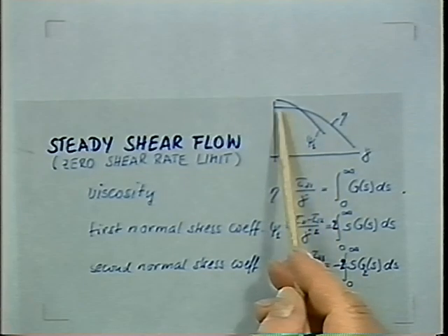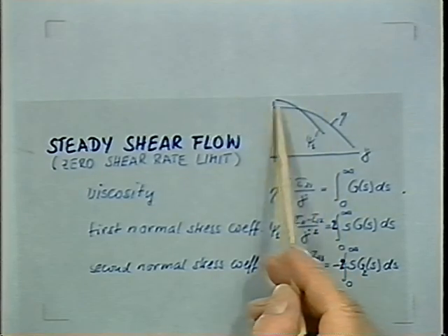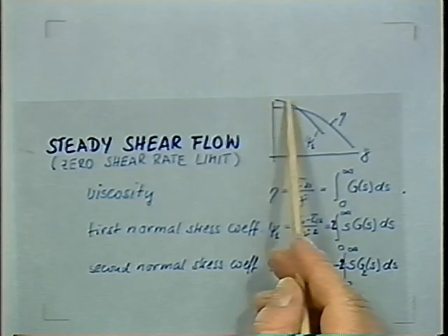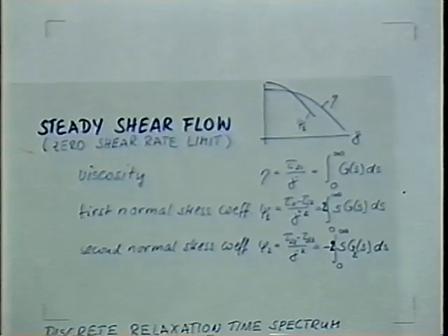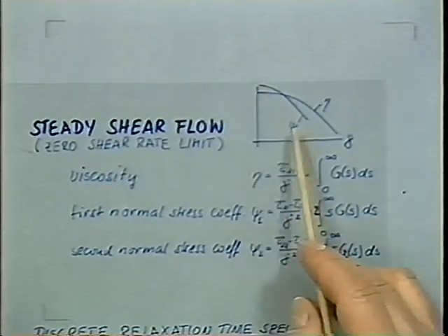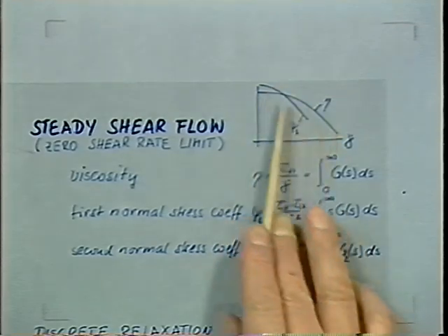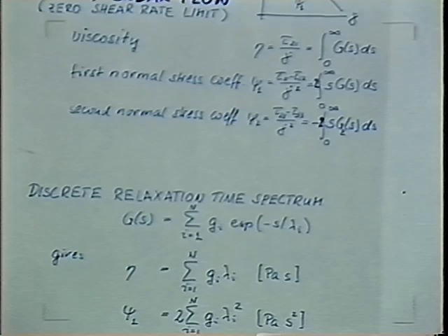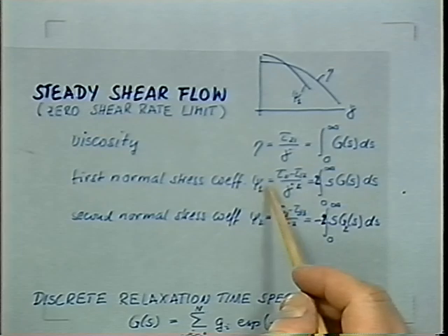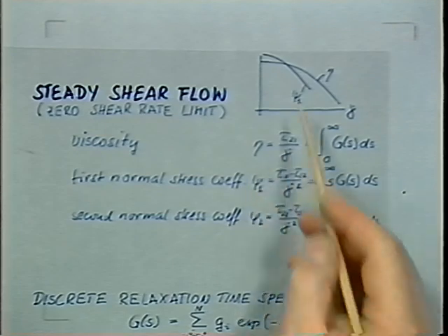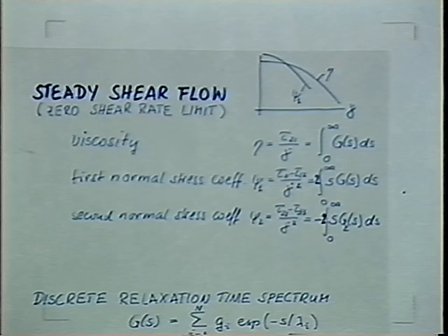So in our picture, we will get the viscosity at low shear rates, the upper limit, and we will get the first normal stress coefficient also at the limit of 0 shear rates. We are talking about the equilibrium part of the experimental spectrum, not the large strain behavior, really. But it's interesting now that with this model, we not only get a viscosity, we also obtain some information about elasticity, and that's new. If you describe the behavior with the rate of deformation tensor, then there is no diagonal term. You don't get any normal stress differences.